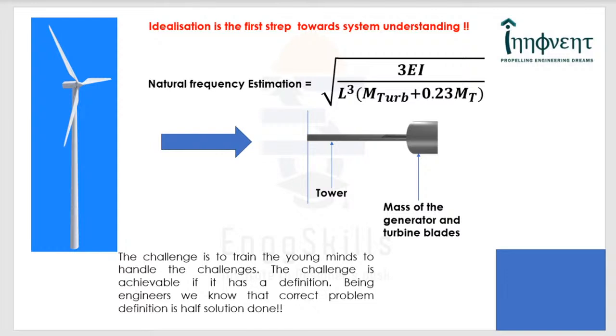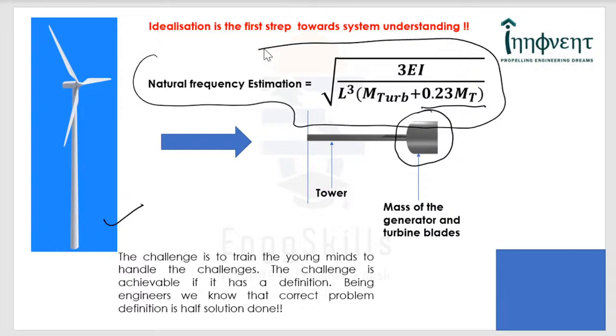One of the first expectations in these industries is your ability to idealize systems, and therefore you can see that I have posted a simple picture here of a windmill, and the windmill is idealized as a cantilevered beam, since the tower has a substantial mass and the mass is lumped at the end, and then we have estimated the natural frequency of this particular system.